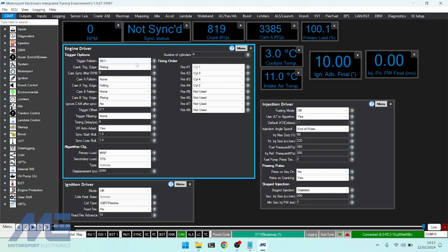That is specific purely to the engine, and you can obtain those from the base maps for the engines we have produced, or with a combination of the trigger scope and using diagnostics, ascertain which edge works best for you.